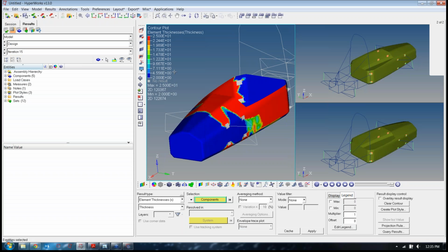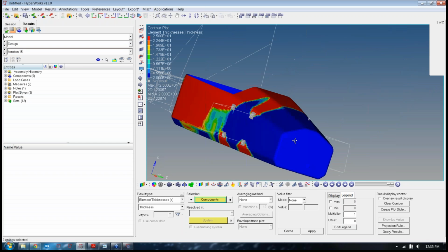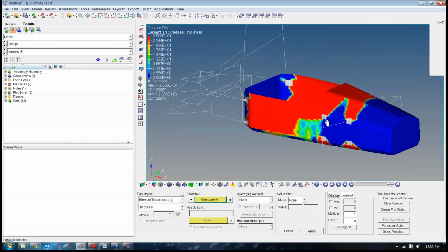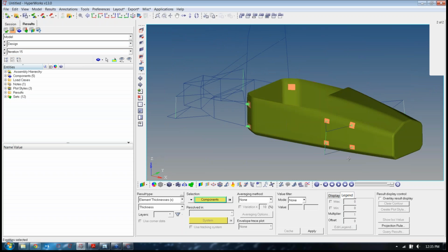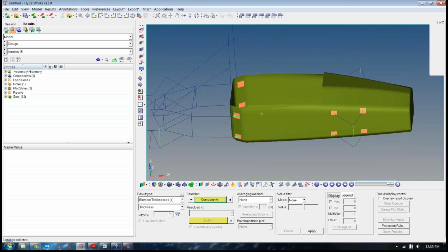Here I've created another page with 3 windows where I've opened up all of the H3D files. Really we're just going to focus on this design file right now, the _des.h3d. When you open this up, it will look just like your model, but underneath the contour panel, you'll have some different options: composite manufacturing constraints, element thickness, orientation thickness, and then ply thickness.